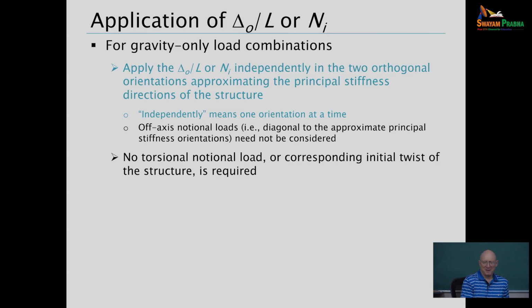And if you look back at your structural mechanics, a cruciform is absolutely the weakest thing you could possibly do in torsion. So in that case, Halverson and Associates actually looked at notional loadings in torsion on the building because they wanted to make sure they stayed out of trouble. But most of the time, unless you've got something special like that, we don't want to bother with it.